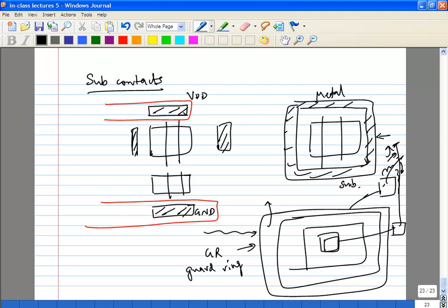There are obviously cases where you may not have so many pads, in which case you would have to decide. So depending on whether the circuit is noisy or whether you're interested in protecting it, you'll have to decide to group the grounds together. That is a totally different topic by itself. That is something you definitely will have to make a choice on. If it is a very sensitive circuit, most people would prefer to connect its own substrate to its own ground, okay, rather than connect it to the guard ring, especially if there's a noisy circuit.